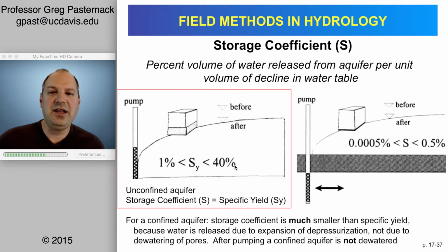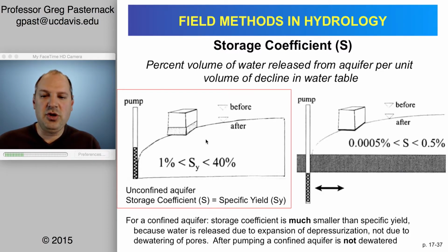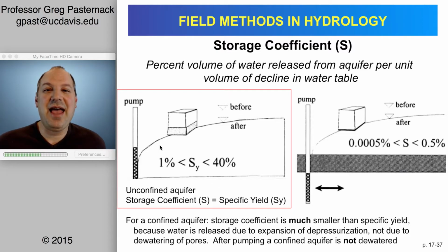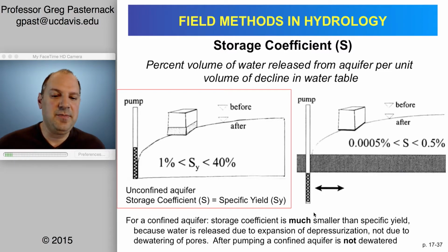Again, depending on the grain size and texture of that sediment, you can draw out quite a lot. However, unconfined aquifer water is usually fairly contaminated, right? It's pretty close to the surface, so whatever is going in is going to be there to contaminate it. A confined aquifer is going to be deeper and it's going to be isolated, so unless the source area is subjected to contamination, this is your really clean drinking water.